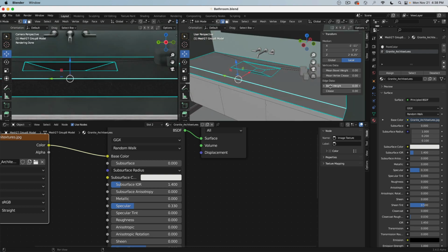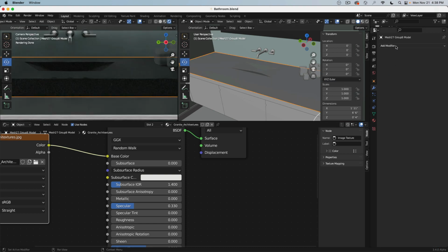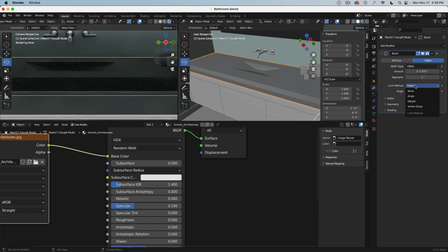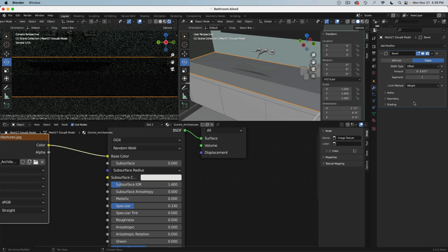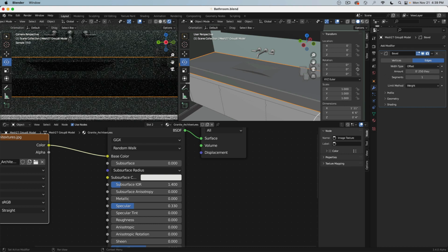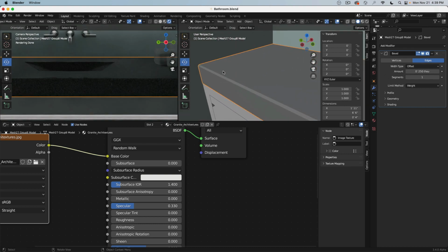And then this line I can give a bevel weight. There we are. So with this bevel weight, if I give this object now a bevel modifier, and then I say only to the weight, please be maybe 0.25 of an inch. You see there, it actually beveled that for me.